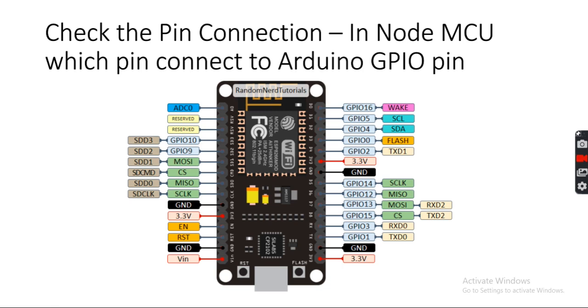So this table is very important. Whenever you are making use of any of the GPIO ports, you have to use this number. These numbers you have to make use of in your Arduino code, and not these numbers.